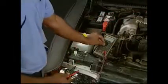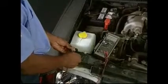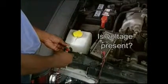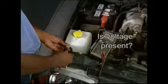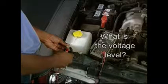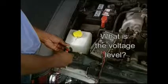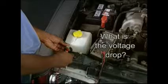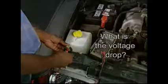Voltage is the difference in the electrical charge between 2 points. Measuring voltage allows you to answer the following questions. Is voltage present? The presence of voltage tells you that the circuit is delivering voltage from the source to the point you are testing. What is the voltage level? The voltage level tells you whether the proper voltage is arriving at the point of the circuit that you are testing. And what is the voltage drop? The voltage drop tells you how much of the voltage is being consumed by the component.